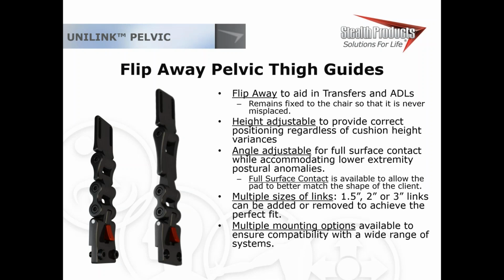Yes. Quick question, sorry. On this version, the flip away version, are we able to reposition that swing away point along the links, or is that a fixed position on that swing away? In this case, this is a fixed position. So this one is done basically by taking our standard traditional lateral and flipping it up. Exact same hardware, different mount. So your flip away mechanism is a mount version and not an inline link. The inline link could be added to this if needed, though.